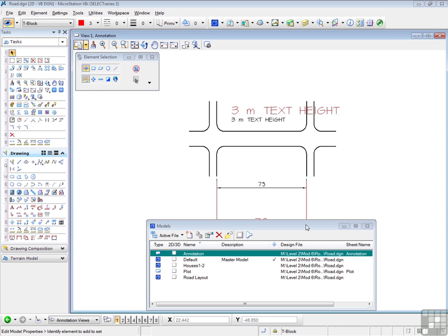Now, on the surface, this method seems to be more efficient, since you don't need to calculate the pre-print text height, as we have done in this example. However, please note that scaling up text and dimensions by any scale factor can cause havoc in a design, especially when text or dimensions are very congested. Use either of these methods with caution and make some test runs before committing to a final scale change. Let me show you again what I mean.